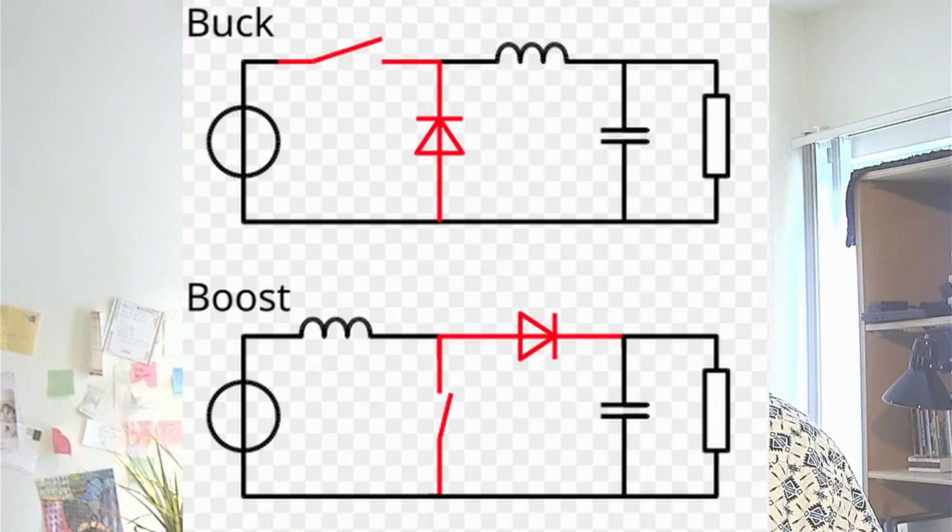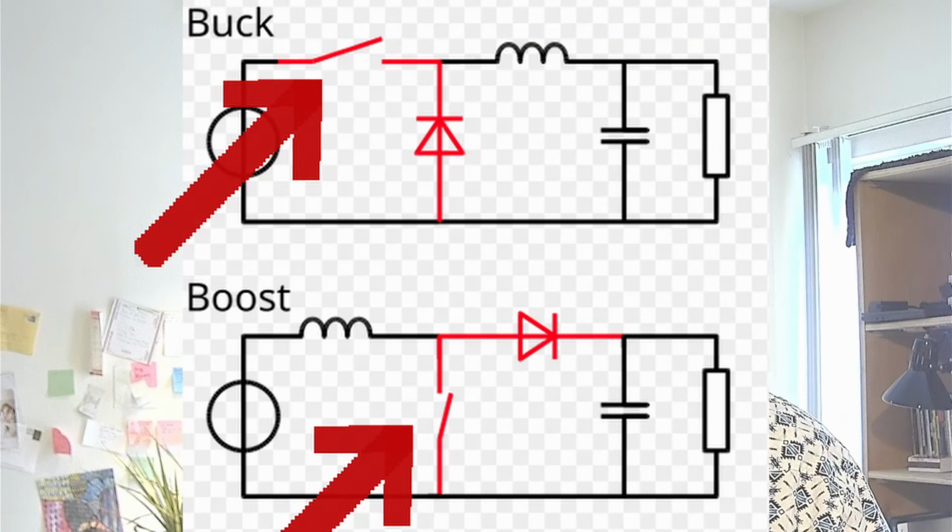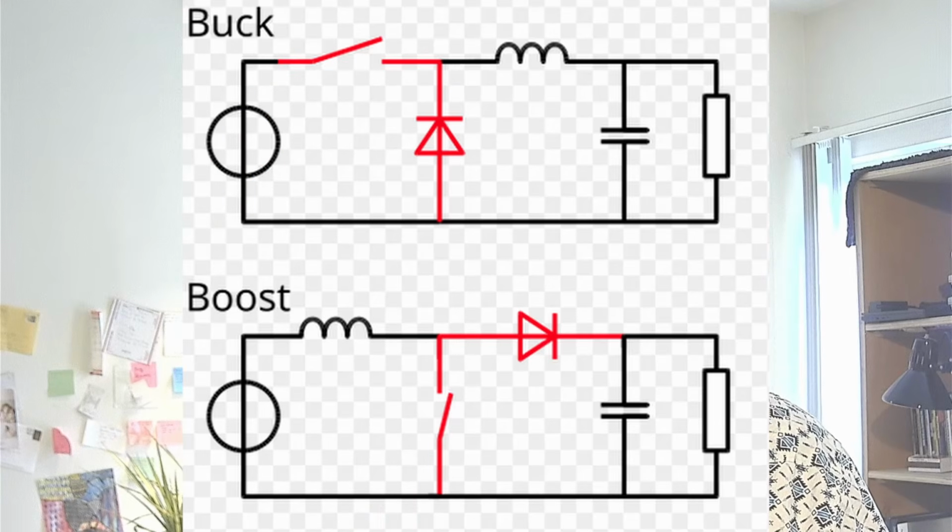In this case, you'll have something like, say, a buck converter. You might also have a boost converter. Both of these operate by turning a switch on and off. That's all you do. Now you do still need to monitor the process value, the output voltage, the input voltage, but for the most part you're just deciding how long is that switch going to be closed. You close the switch, the current will rise in some inductor, and then you open the switch and the current will fall. That's usually how it works.